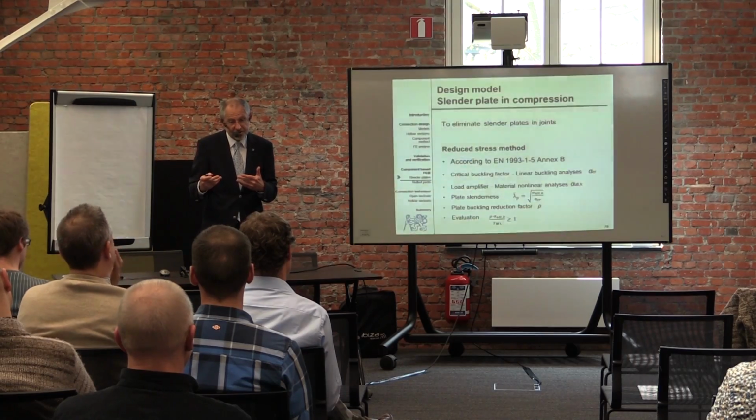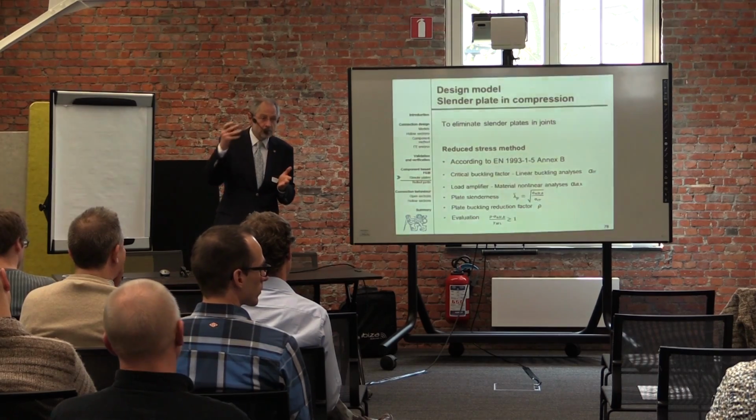And it's very simple. Of course, we have a lot of other ideas for what procedure to use, effective thickness, effective width procedure, which is in Eurocode, or effective stress prediction. But this is for post-buckling.